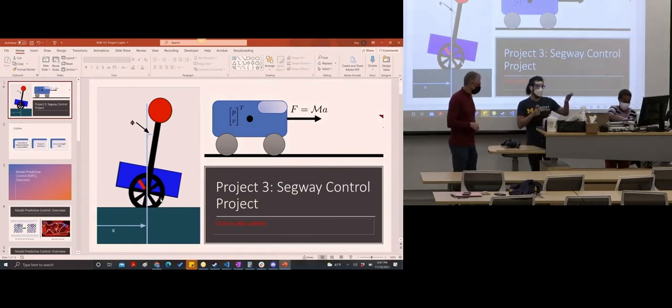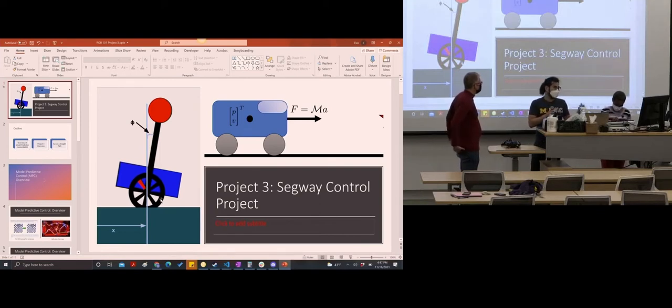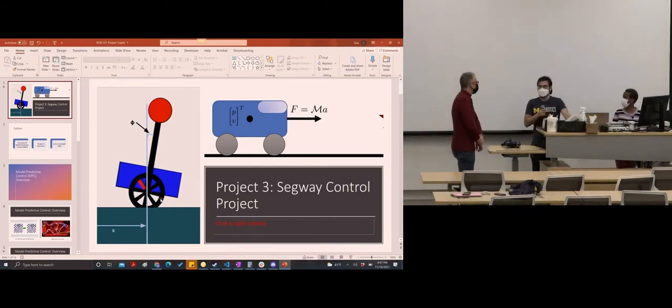That actually brings the question back to why do we use target-based calibration? There are actually different works that are targetless. The reason why we use target-based calibration is because we want to calibrate the sensor everywhere, anywhere we want. For example, we can bring the target to the forest, we can calibrate it, but for those targetless calibration, I highly doubt they can do it in a forest.